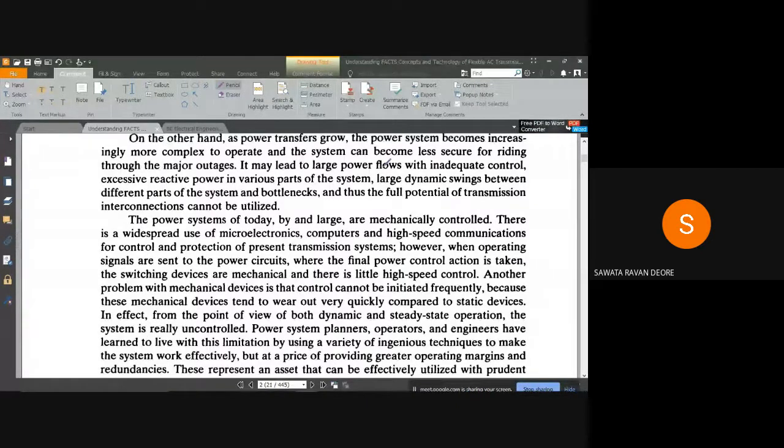So there is a communication of that signal from the CT to the computer. That should again be high speed, because what is the time constant of the CT? What is the speed of transfer of that signal to the computer? What is the speed of processing of your computer? According to that, whatever output signal the computer gives, it will forward as a controlling signal to the circuit breaker.